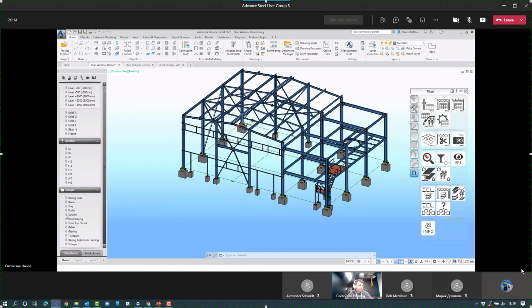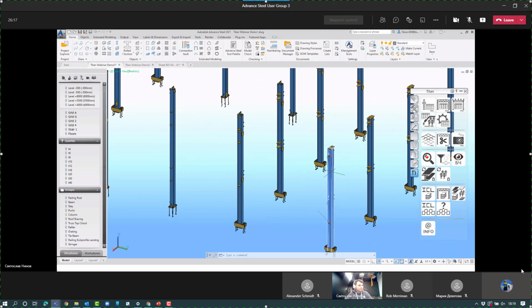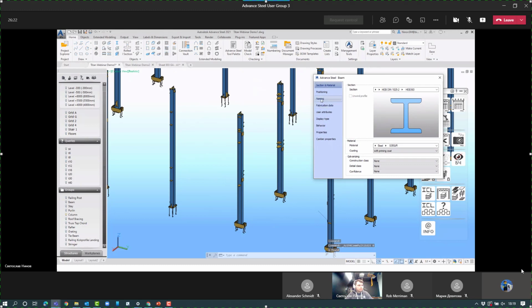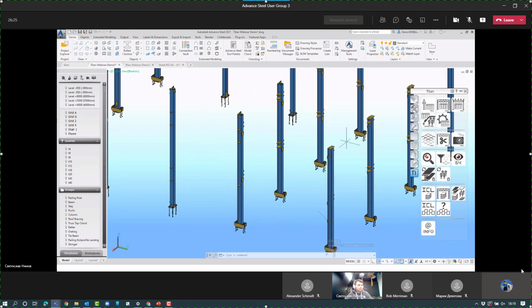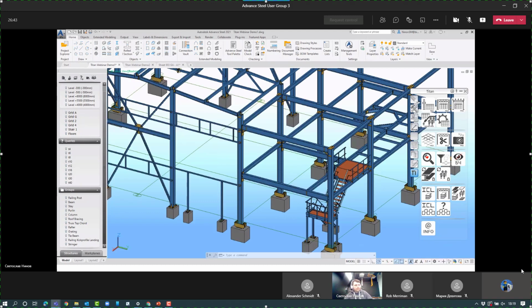For example, you have main part, column, all main part elements with model role column you can set to group, and every connected element goes to group 2. You can use this command to create drawings with processes.